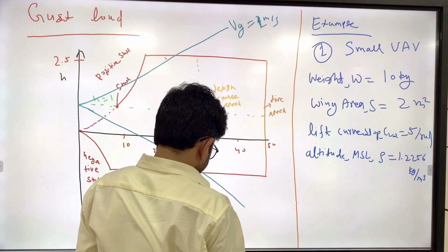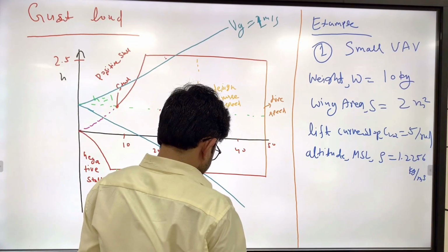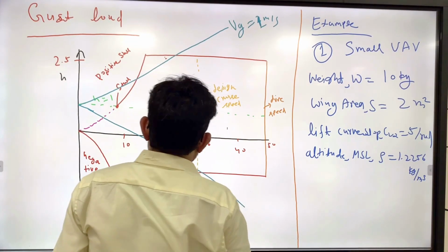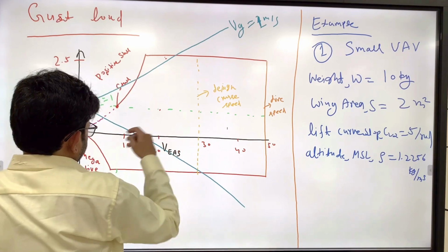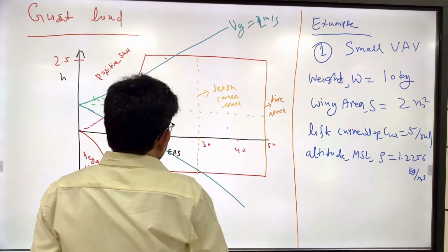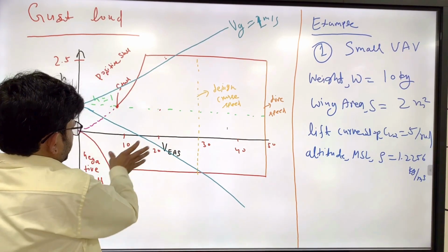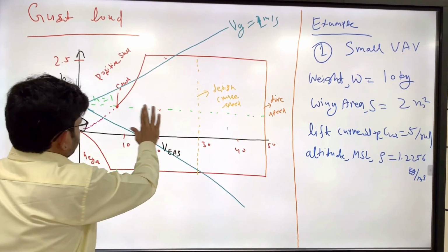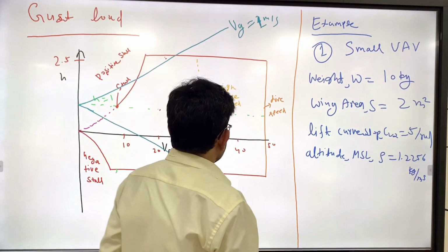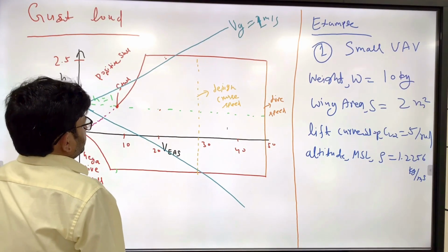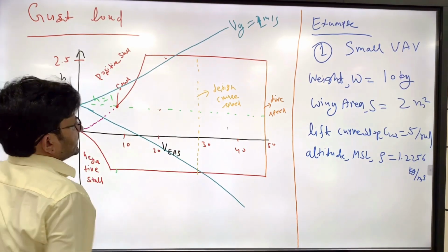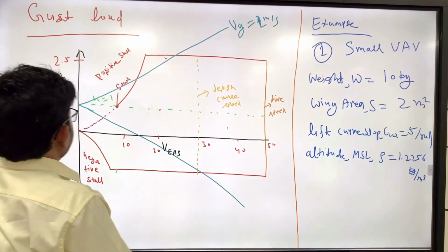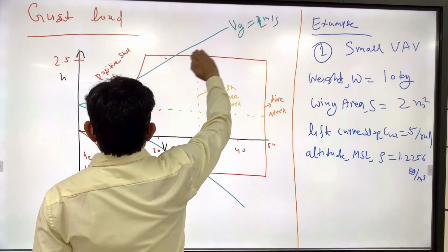So 28 divided by the stall speed is roughly 3.5 times. Let's say you take the design speed, then compute the stall speed. It is your choice. You can take the design speed here or here. It should be more than the stall speed, at least 20% more than the stall speed, right? I hope these things are clear to you, and how you have drawn the gust also.